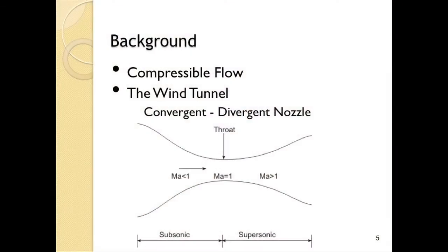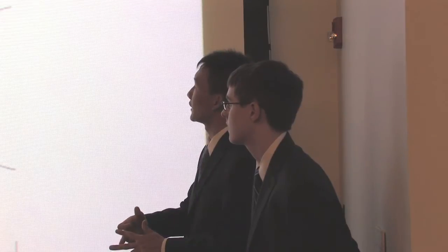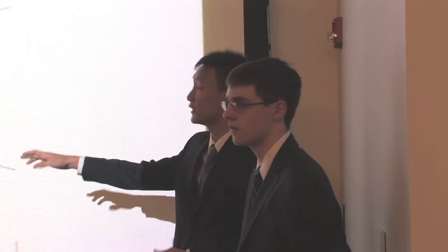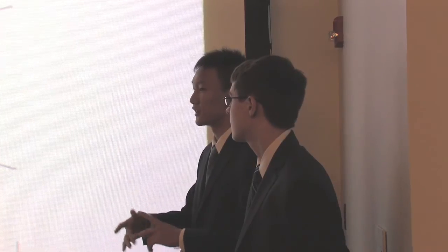There's something called the continuity equation, if you've ever heard of it, and it basically states that the product of the density, the area, and the velocity remains constant throughout the flow. So in the beginning, the reason why velocity increased is because it was traveling slowly, so it was incompressible, and that meant the density remained constant. So if the density remains constant, we only need to consider the product of area and velocity. It remains constant. So as area decreases, velocity must increase.